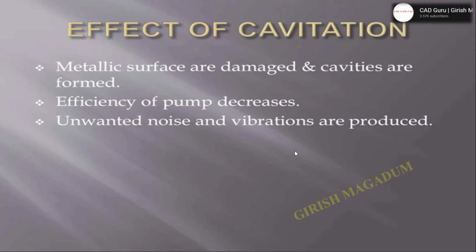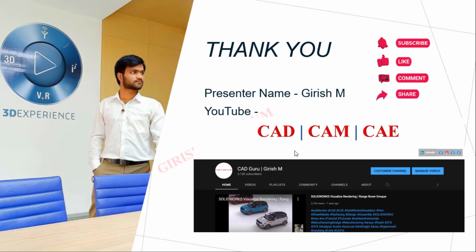These are a few basics, and finally we have the effect of cavitation. The metallic surfaces are damaged and cavities are formed. We already saw that. The efficiency of the pump will definitely decrease due to this, and unwanted noise and vibrations are produced. This is the initial stage as well. If you find this, you should change the impellers, make some modifications or replace them.